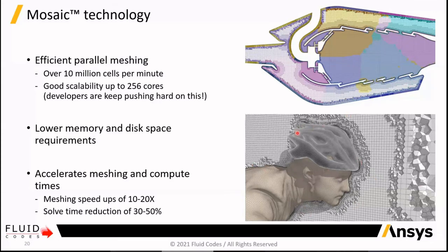As you can see here, the detail of this geometry, the complexity, the transition. We can also play a little bit with the transition. As you can see here, it's an octree Cartesian approach, but here you can see there's not this kind of transition, so we can regulate the transition, conformal or non-conformal. These meshes are both good for Fluent, but in this case we can eventually get a little bit more accuracy. It depends on the application, but we have all the options available, so we can play a little bit with that.